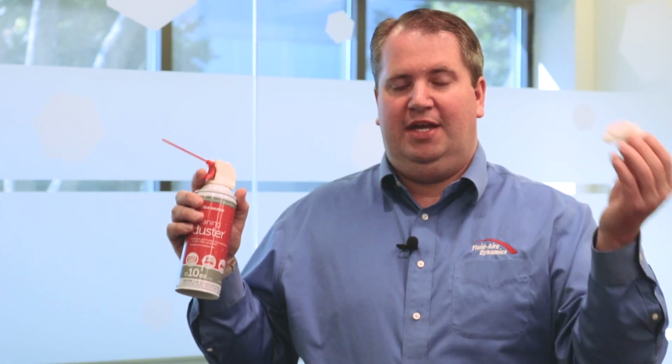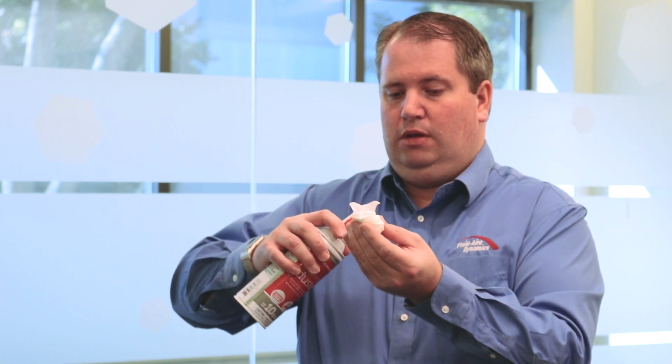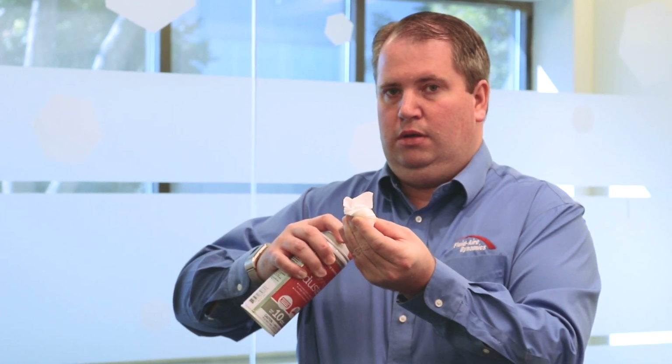What I'm now going to do is take that same 1 CFM and send it through a piece of tissue. What this is going to demonstrate is compressed air going through a muffler in maybe a MAC valve or a spool valve or some cylinder that's constantly leaking. The point here is you may not always be able to just use your hearing. You may need to use some form of data logging or metering.